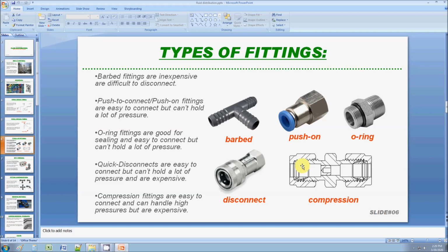This was a revolutionary design where the ferrules bite into the tube and cause a seal. Meaning you no longer need to torque the entire assembly to disassemble. You just torque this nut, it releases the ferrule, and you can connect it and reconnect it as many times as you like. So this was revolutionary, and it caused so many companies to become billion-dollar companies just from this innovation.